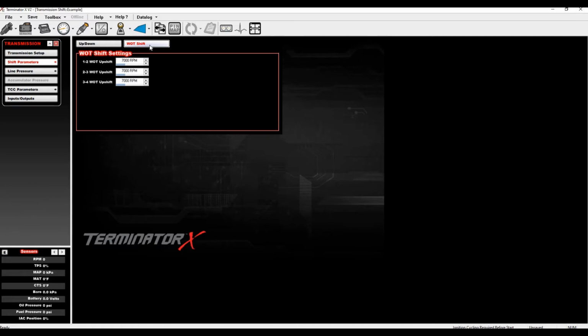I usually will take 1500 or so RPM out of them relative to where I want them to shift, just to start with, and then go from there, working my way back up. That said, 4L80s are typically not quite as bad, but I've definitely had some doozies.